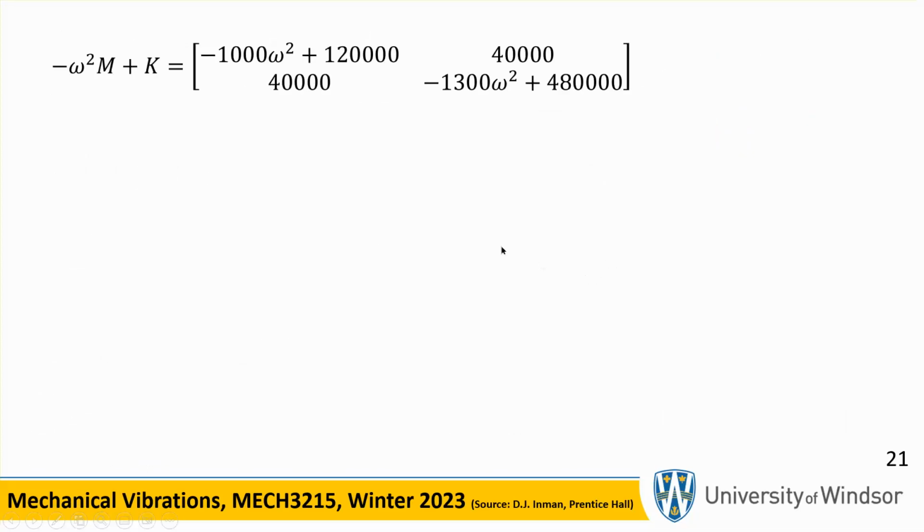Okay, there we are. You have to find the natural frequencies. So the mother of all equations for natural frequencies is right here: the determinant of minus omega squared M plus K equal to 0. Patiently solve for the two frequencies, right there.